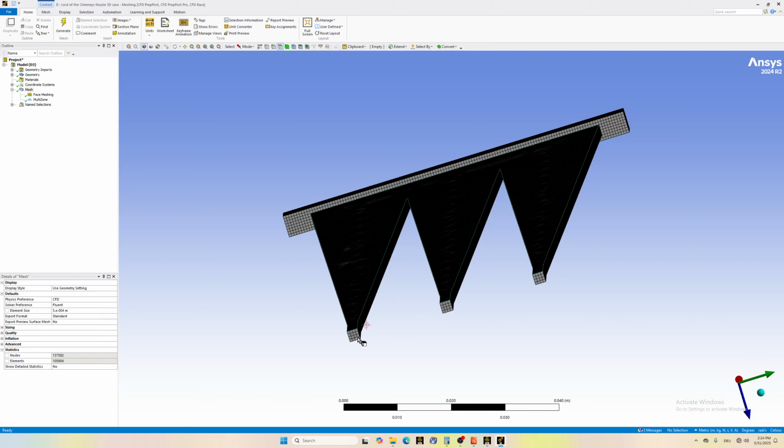Now, if you don't intend to put different pressures on each inlet, you can select all three of them and give them a unique name. So you can edit all of them at the same time. I mean, you can define the properties of these boundaries at the same time. So the same pressure, for instance. If you want to put different pressures or different gases, then you need to give them unique names.